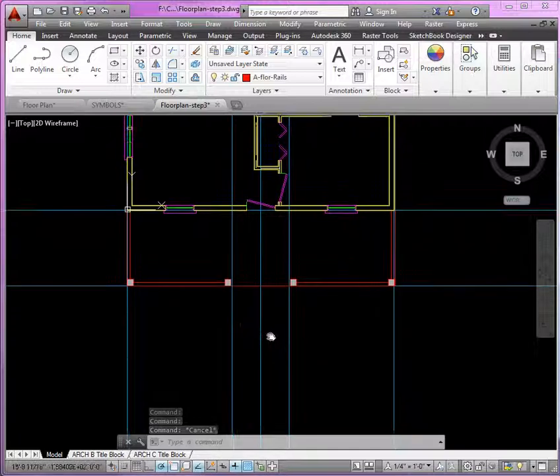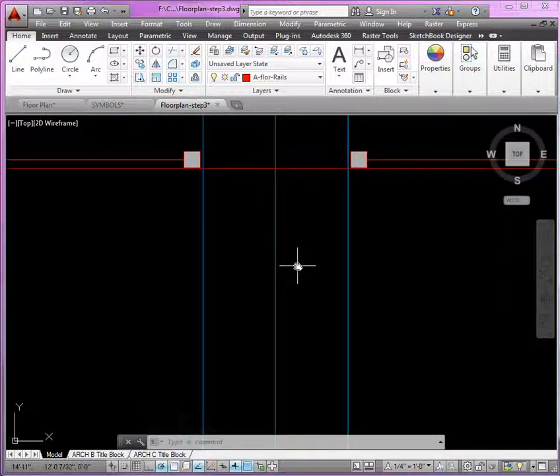And as we focus our attention on the stairs again, what you'll see is we have 6-foot wide stairs there, and then we've got a typical 14-inch offset. And again, depending on the actual elevation you're trying to create stairs for, there will be a particular formula to define the dimensions for your tread and your riser.